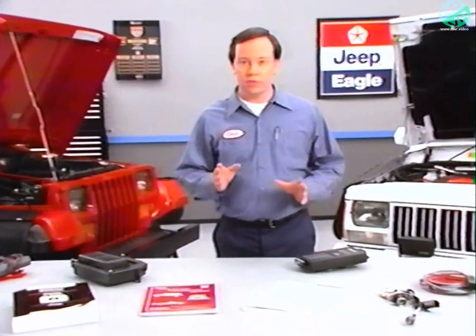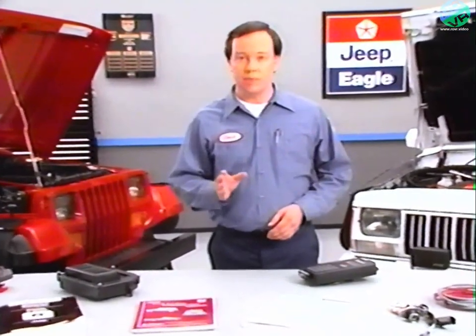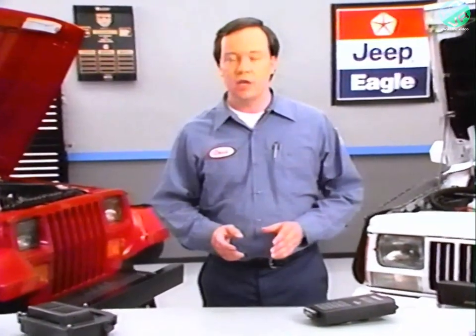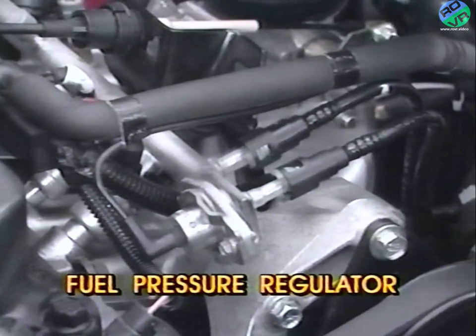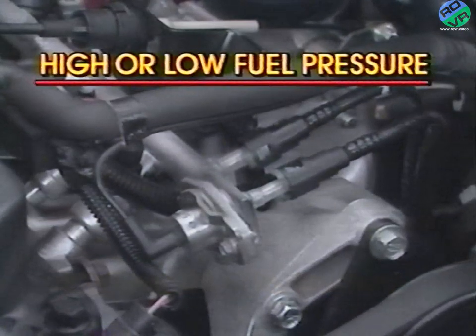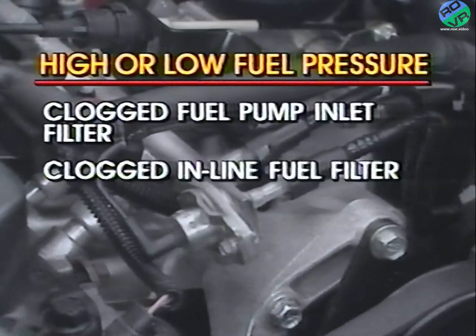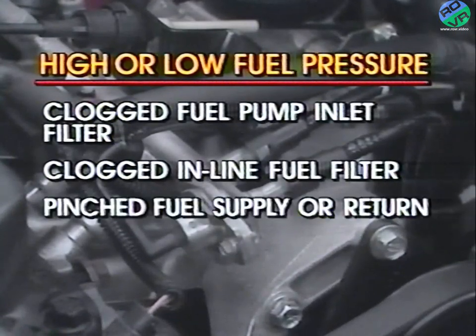There are a number of circuits and systems that are not directly monitored by the engine controller, but those systems could have malfunctions that cause drivability problems. It's also very important to remember that a problem in a non-monitored system may cause a fault to be displayed in a monitored system. For example, the engine controller does not monitor fuel pressure. High or low fuel pressure can be caused by a clogged fuel pump inlet filter, a clogged inline fuel filter, or a pinched fuel supply or return line.